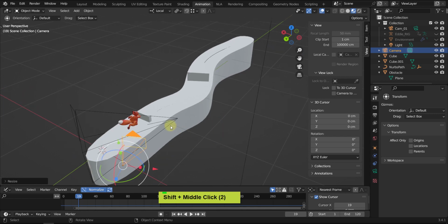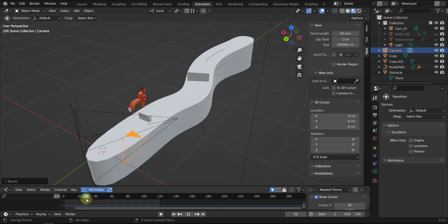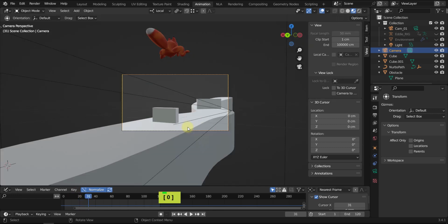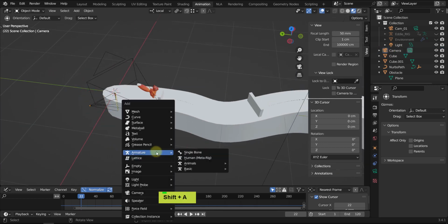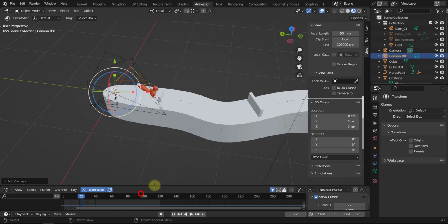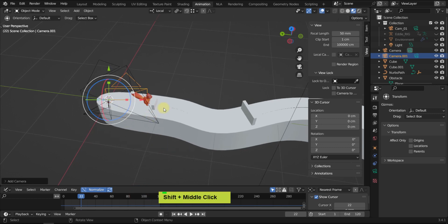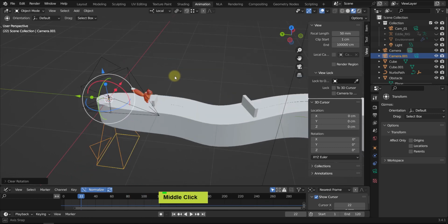And definitely we want to switch between the cameras, but right now it is just the first camera. We have a couple moments. All right, so we want to show this. Let me see it, if it's visible or not. The figure comes in and then jumps over, but we want to create a new camera for that jump. All right, so I'm just creating a new one. So Shift A and R for a camera. Here we are. This is what I wanted to show. So there's another camera. And let me just Alt R, reset rotation.